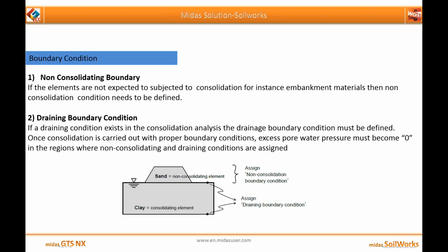For example, if you are using drains, you will assign the draining boundary condition to the drains. Also, for the top and bottom layers of the clay, as you can see in the figure, you have to assign the draining boundary condition. What it says is that there should not be any excess pore water pressure, zero, in the regions once this boundary condition has been assigned. It will be more clear when I elaborate on it in the demonstration part.